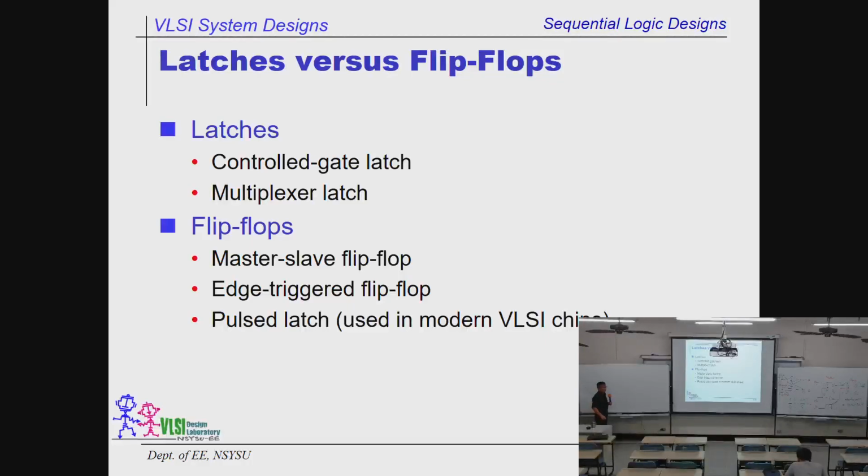Okay, so we are going to make a short summary about the comparison of latches versus flip-flops. For latches, we have the control gate latch, just like the one we drew on the board, and the other type is the multiplexer-based latch. We're going to see it very soon. But in my experience, the multiplexer latch is not that welcome, because it has too many problems: you need a control line, and it makes a lot of connections.